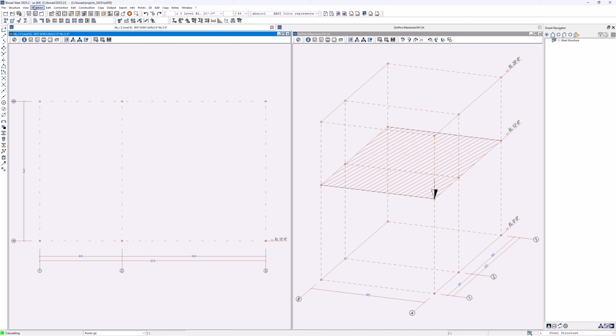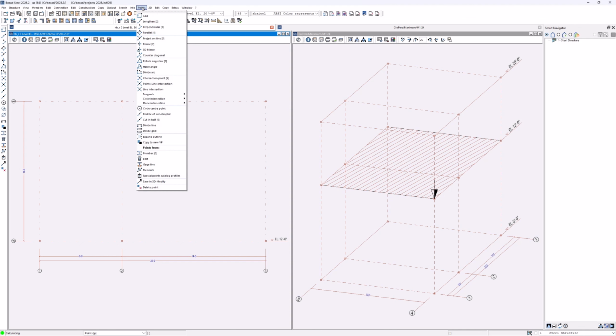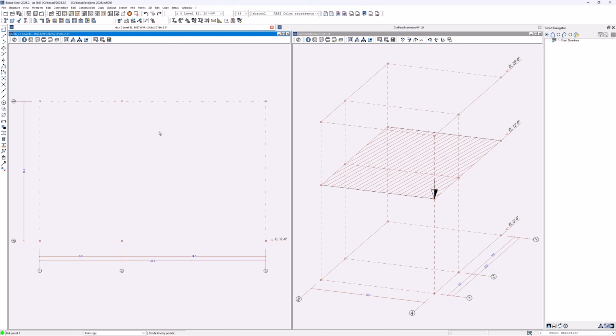I can start, of course, creating the various columns and a couple of beams on the outside, but there will be all these intermediate beams. I will need some kind of snapping references in there. That's where the points come in again. I need equal division, divide line.